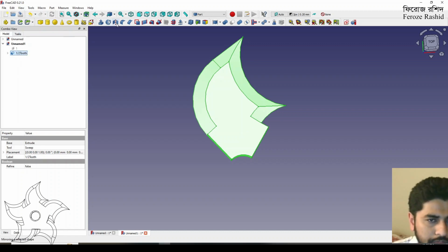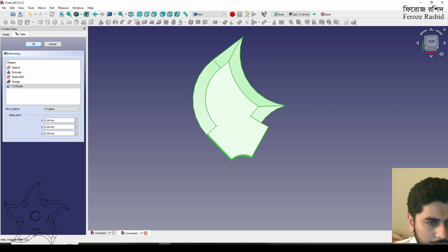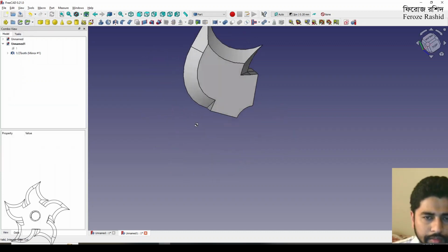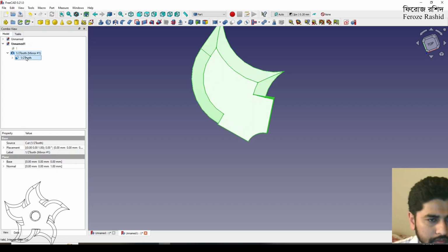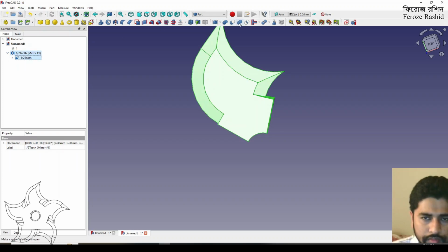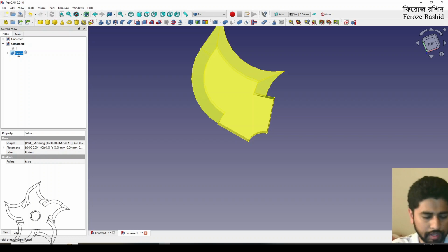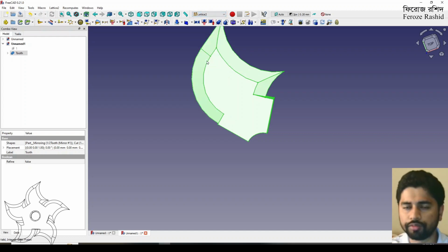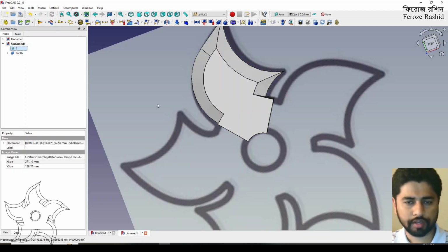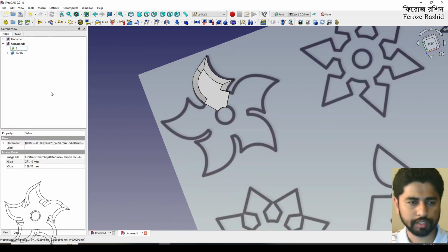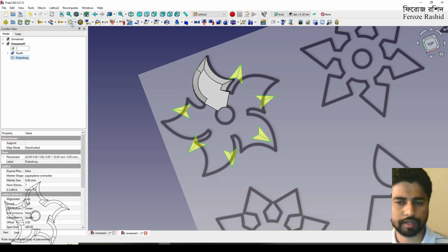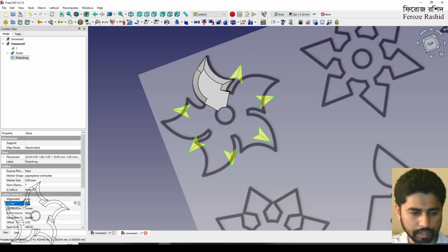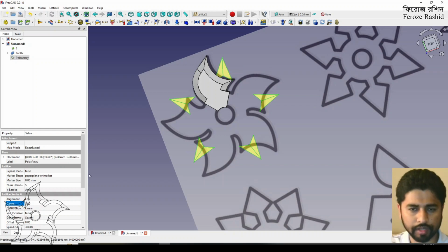I want to mirror that part on XY plane, and that becomes our full tooth. Union those, make it a tooth. Okay. Now I want to use the lattice workbench to make 5 more replications. So bring in the polar array. For the count, let's make it 5. Okay.